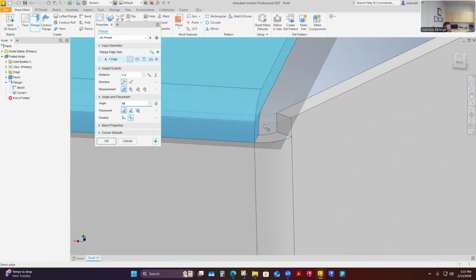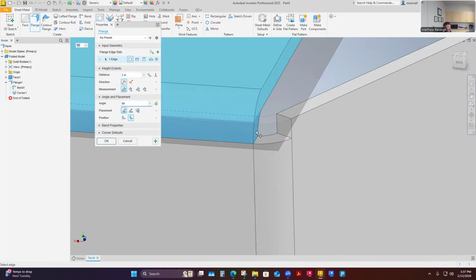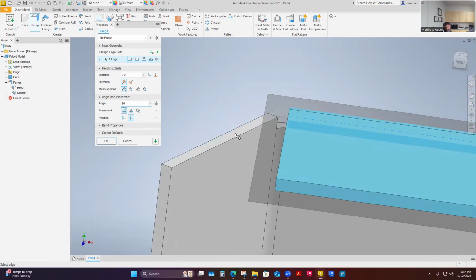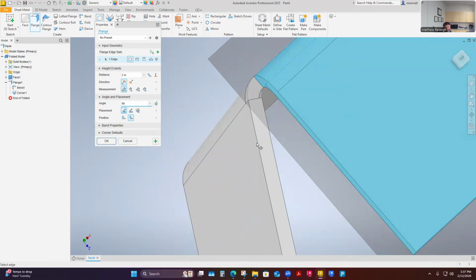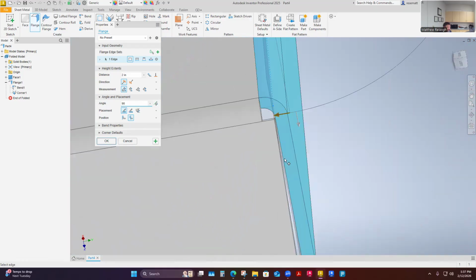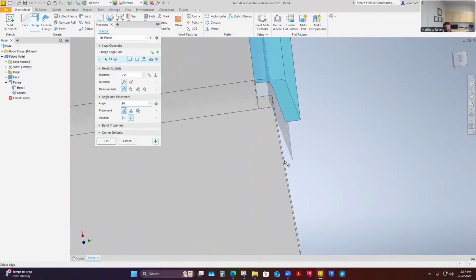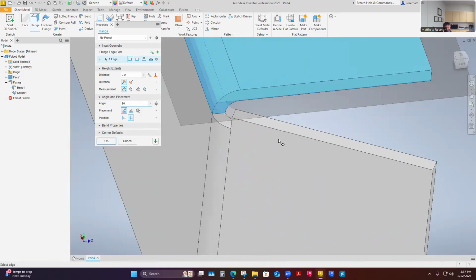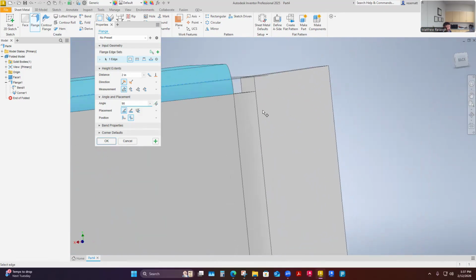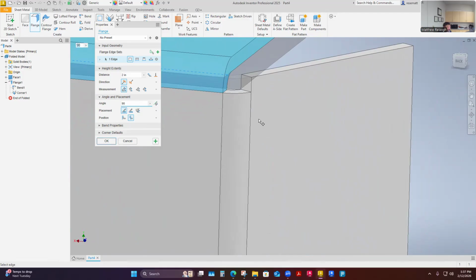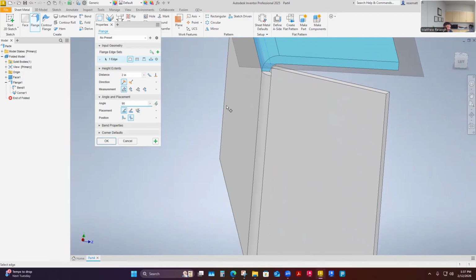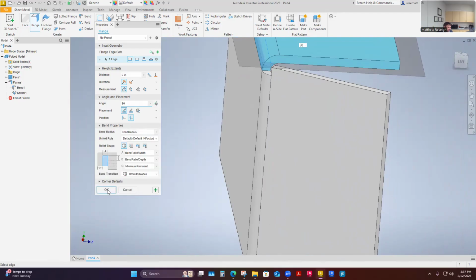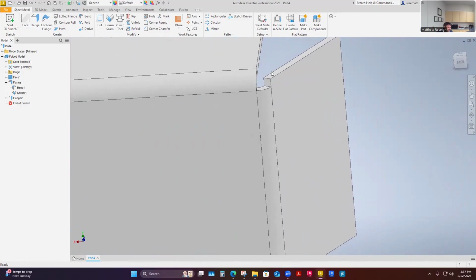And there you start to see some of that relief automatically added because that's just the way it's programmed. It's like, oh, I have to add a relief in this corner situation. If I don't want it, it does remove material, and it can remove a substantial amount that maybe I don't want to remove. It is made to be a relief so I don't get any extra stress on my material or my machine to bend. I think everything else he leaves the same. He doesn't even change any of this. His may not show this though.